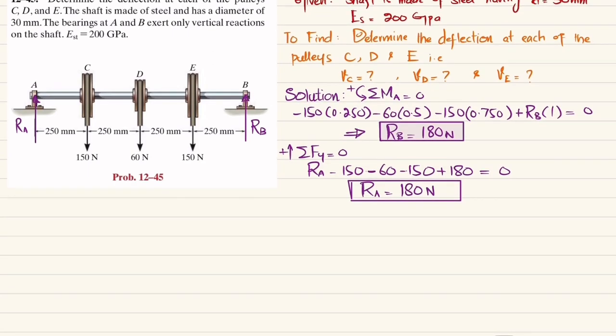So what we will do is find the equation of the elastic curve, because we have to find deflection. For that we need the equation of the elastic curve, which can be obtained using the moment equation, and we will find this moment by using singularity functions. M can be found by using singularity functions, or you can also call it Macaulay's method. For that we need a table that is available in chapter number 12.